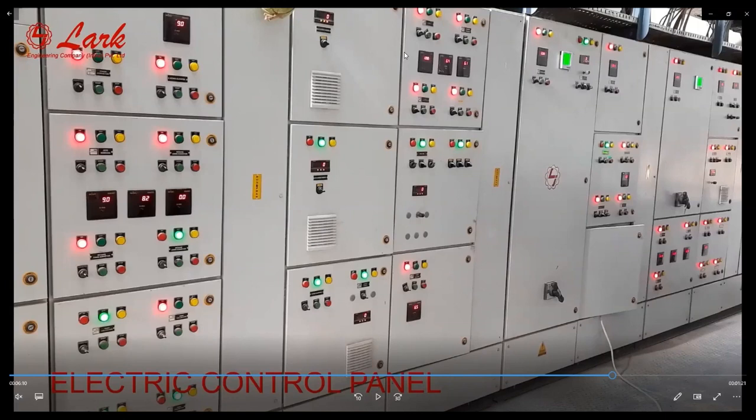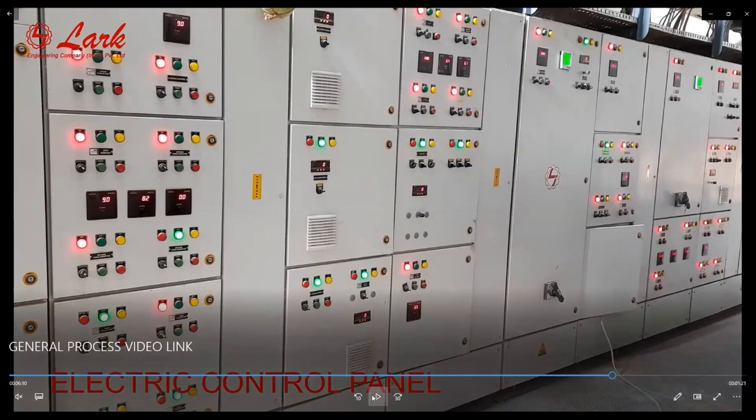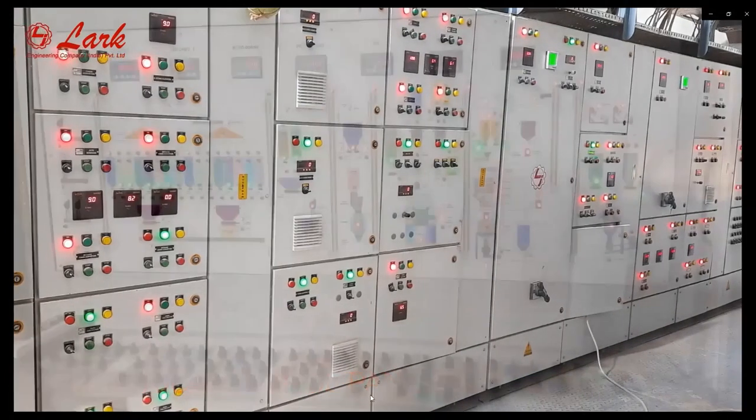So we have to check whether the hammer mill is running ideally or consuming idle power with respect to the production, or whether the pellet mill is performing less with respect to efficiency and power consumption. So we can add energy meters even in the existing panels with the help of our electricians to monitor the power consumption trend of our machines.